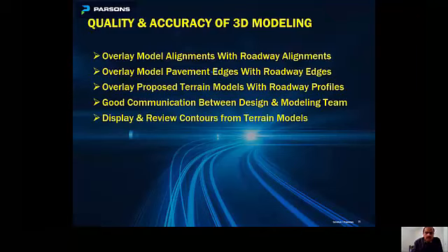And then it's always a good idea to display the contours once the terrain model gets created from the model. It's always a good idea to generate the contours and then review the contours thoroughly. We would also have to check the contours to make sure that the low spots and the inlet locations would match, and also that the culvert would line up correctly with the contours.